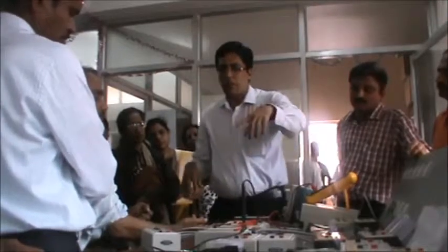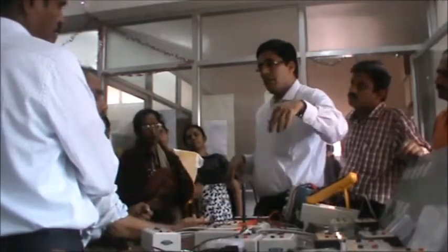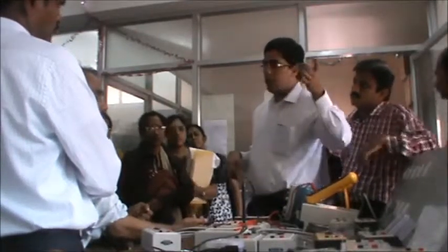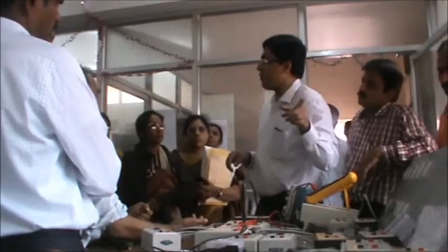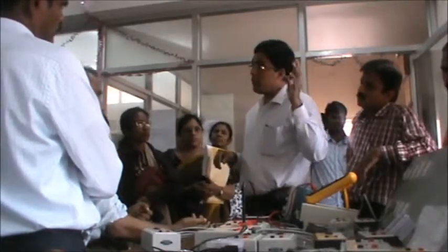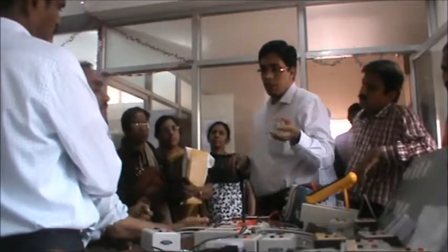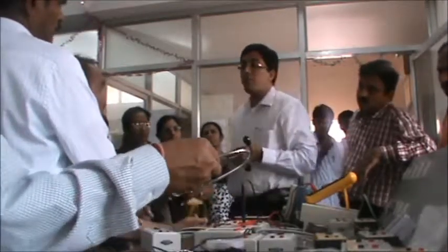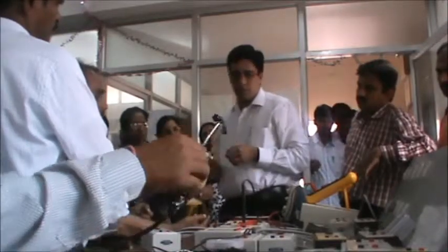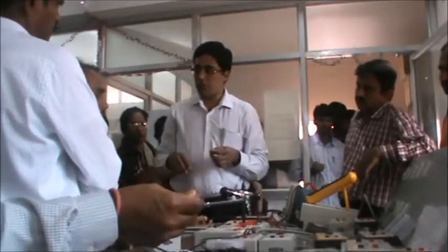Normally these kinds of blocks were used initially by IIT Kharagpur students, wherein the medical doctors have a course in bioinstrumentation. What is the cutoff frequency of the low pass filter? Here we use 50 Hz. We use a second order low pass Butterworth. Second order.